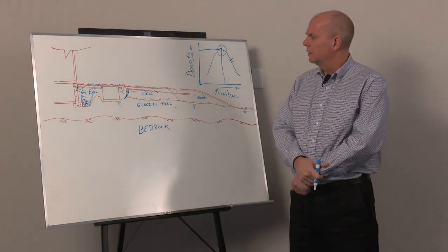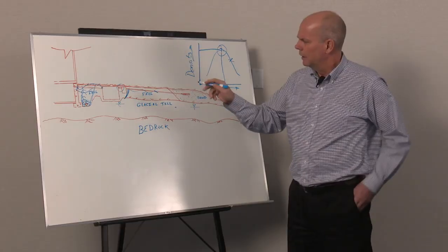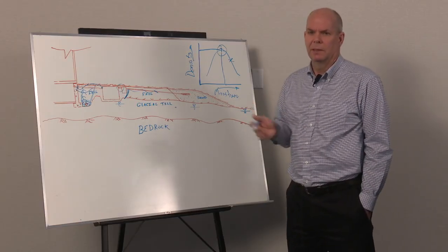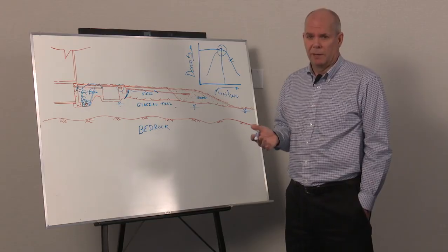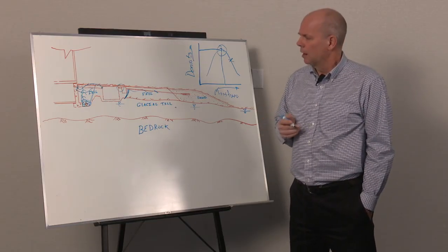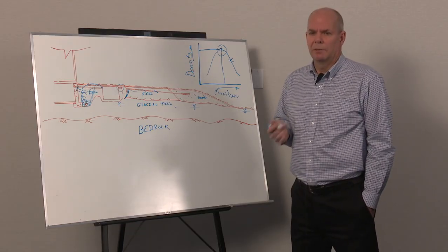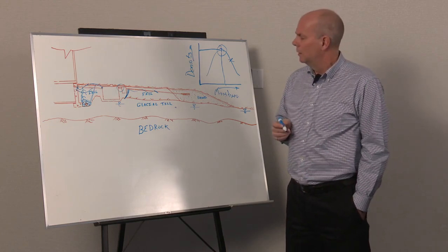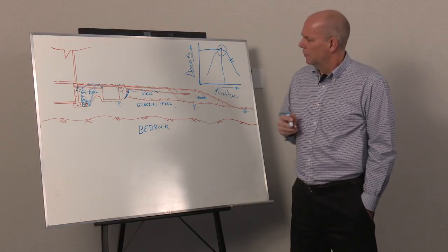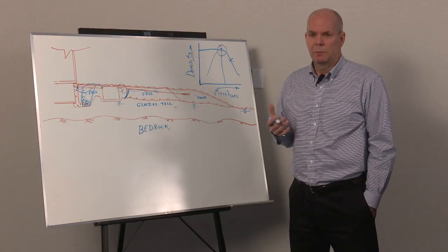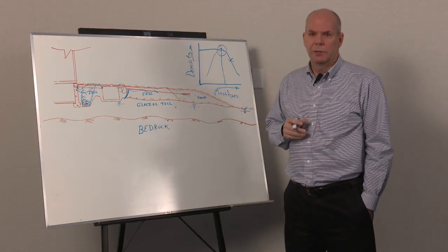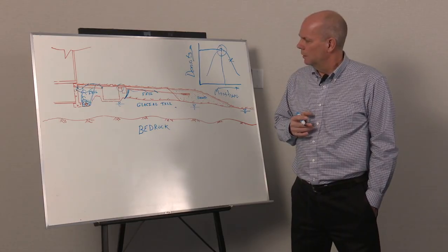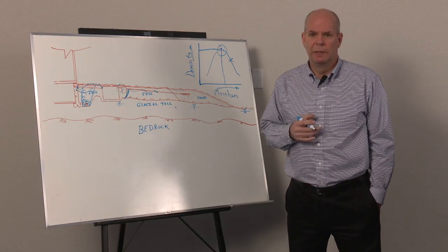So to summarize, I think the main things to watch for are that existing conditions will always cause problems if not looked at in a serious way, to verify that the fills that are already there, if there are fills, are suitable to build on or in. And if not, you have to do enough work to improve them so that it's not going to affect your system. When you're dealing with materials that have the potential to cause problems if not placed right, be cognizant of the moisture content, make sure you're placing it in lifts, compacting it with the proper equipment, and you should have no real problems. Thank you for your time.